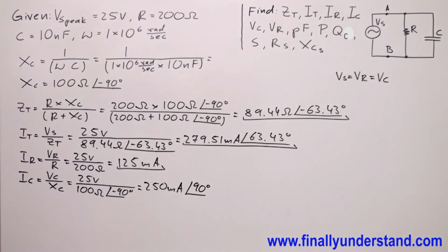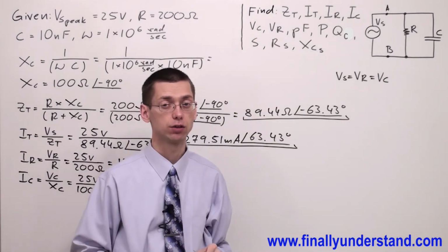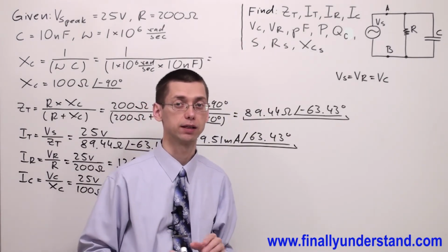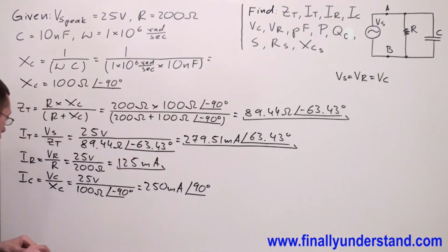Someone is going to say, okay, we can continue. We can go to the voltages or power factor. Okay, we can go, but it's always good to check if our answers are correct. We're supposed to verify these answers by using KCL, Kirchhoff current law.